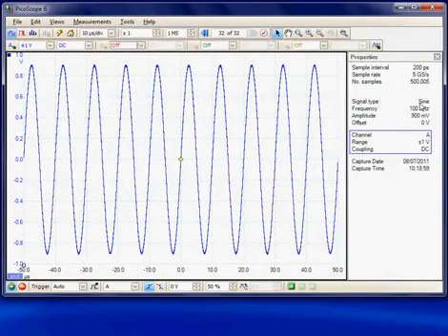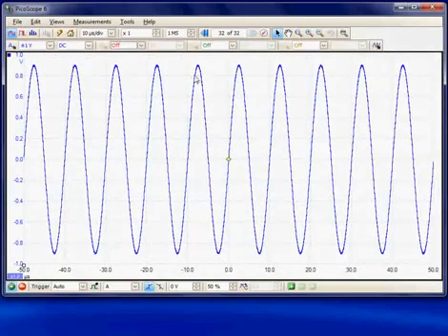The second set is the arbitrary waveform generator. So here we can see the sine wave, 100 kilohertz, 900 millivolts again with zero offset. The third grouping is the channel A input. So we can see it's in blue, and this is highlighted in blue. So we see channel A plus or minus 1 volt and DC. This again can be minimized to keep the area available for the waveform display to be always maximized.